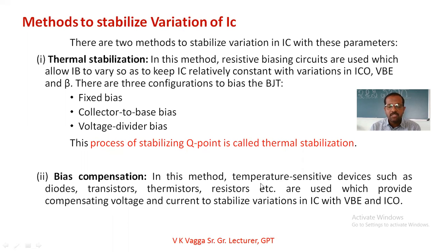In this method, temperature sensitive devices such as diodes, transistors, and thermistors are used, which provide the compensating voltage and current to stabilize the IC with VBE and ICO.